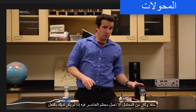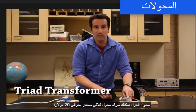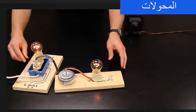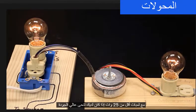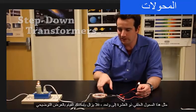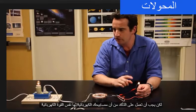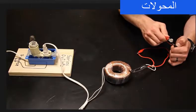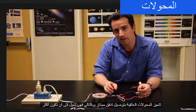If you don't already own an isolation transformer, you can buy a small triad transformer for about $20. Its only shortcoming is it has a small power rating and should only be used with bulbs of less than 25 watts. If you have a high-quality step-down transformer like this 10:1 toroidal, then you can still do the demo, but you should work to ensure that your light bulbs have the same wattage. Toroidal transformers have excellent flux linkage, and so they tend to be more efficient.